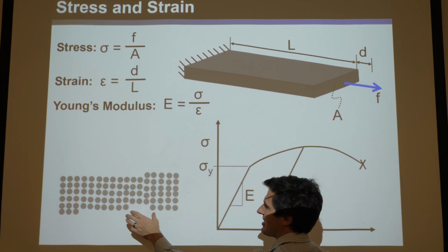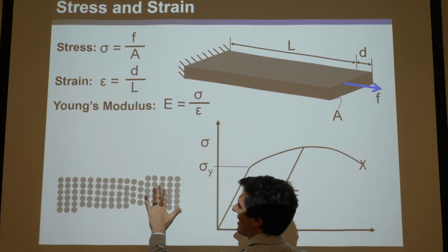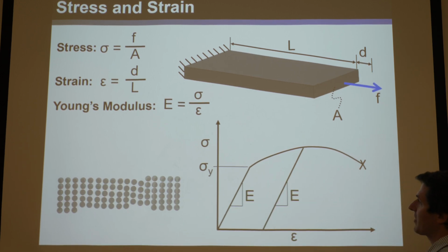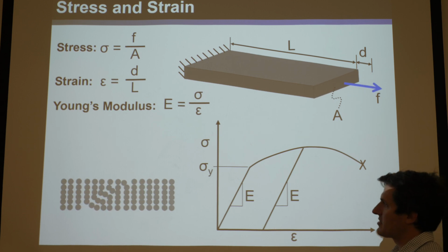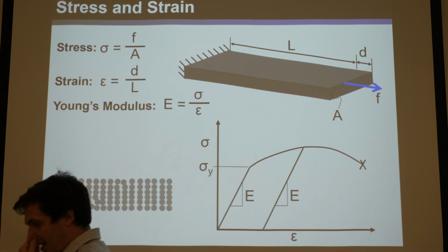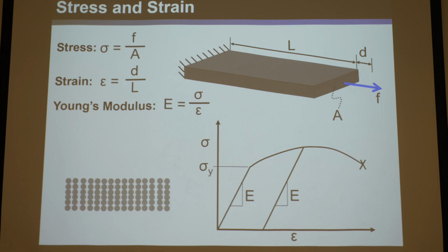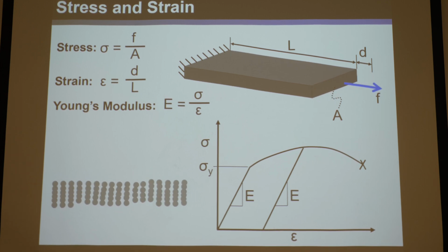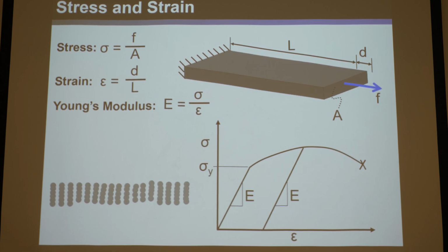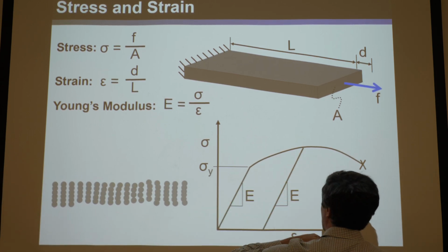That's what you see here. So you can see it right here. It's stretching. You can see it plastically deforming. Now we're going to unload it, and it comes back and it's at rest, but it's a little bit longer. It's permanently deformed. So it's important to understand how that works and how these atoms, as they break and dislocate, are releasing internal friction, and they create problems, right? They generate heat, and of course it's not a repeatable process. So the precision and repeatability dies off here.